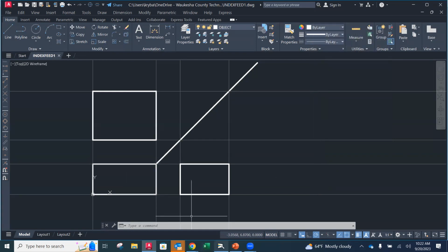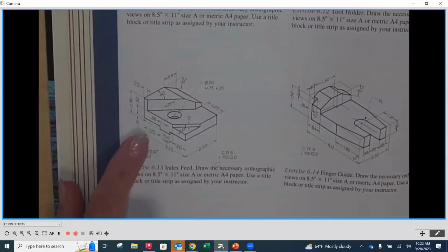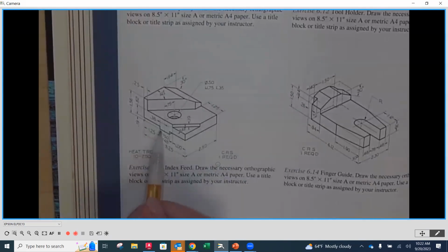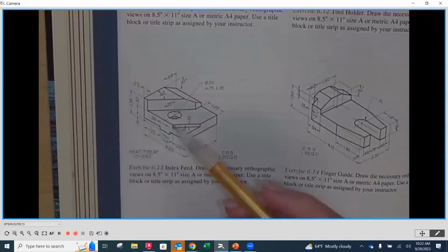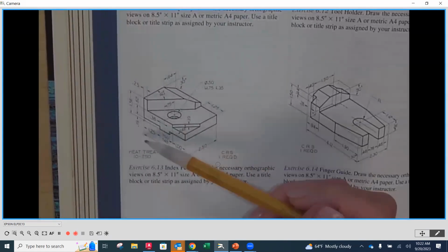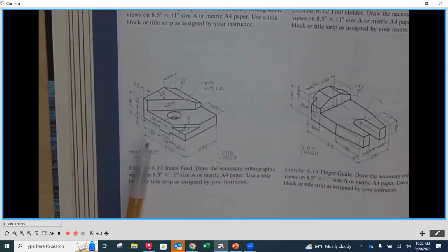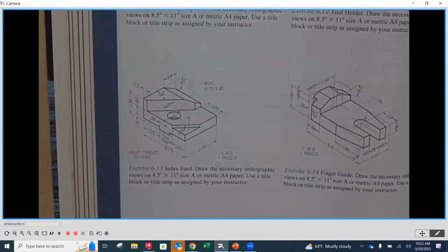All right. Let's revisit our drawing and see what we want to do. So again, I'm going to continue to focus in the front view until I can't. Okay. So what I'm going to create is this little cutout, if you would, of the 0.75. So I do know that from that bottom, because I created the rectangle to be along this bottom, I'm going to offset up 0.19, okay, to get that gap. And then I'm going to offset over 1.25, and then a distance apart of 1.75, or I'm sorry, of 0.75.